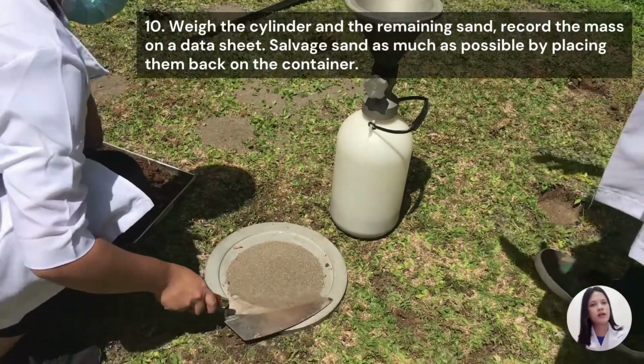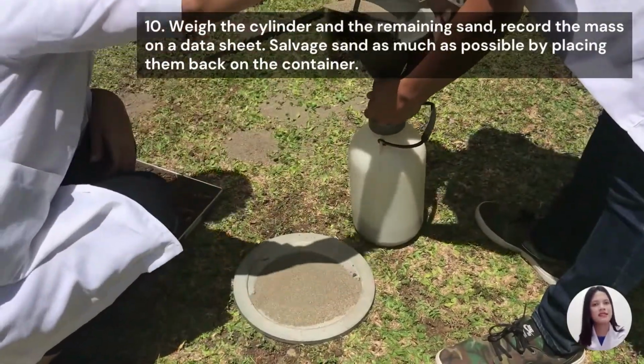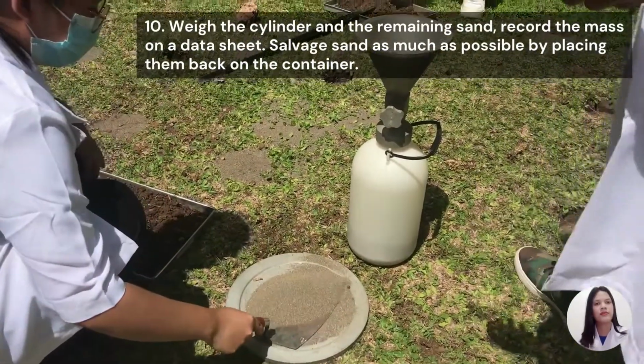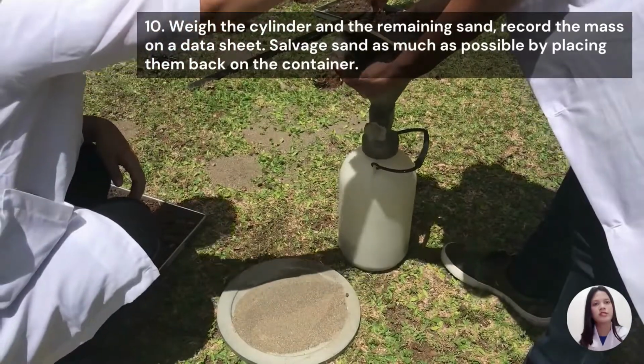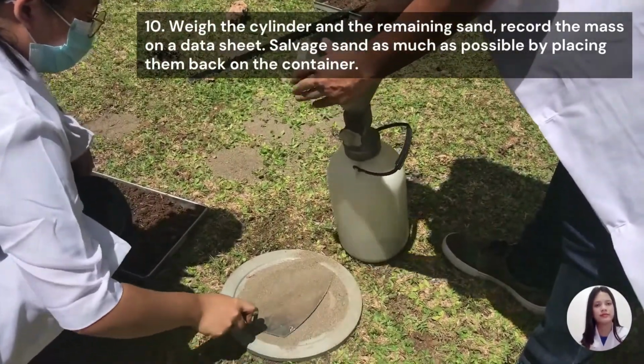Salvage sand as much as possible by placing it back in the container. Then lastly, repeat steps 5 to 10 for at least 2 more trials. After getting all the necessary data, the bulk density, moisture content, and dry density of the soil may be determined.